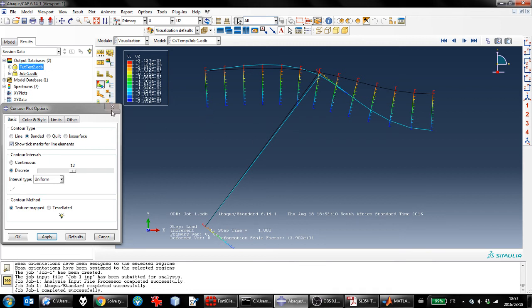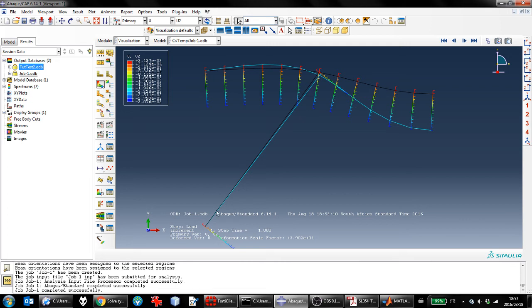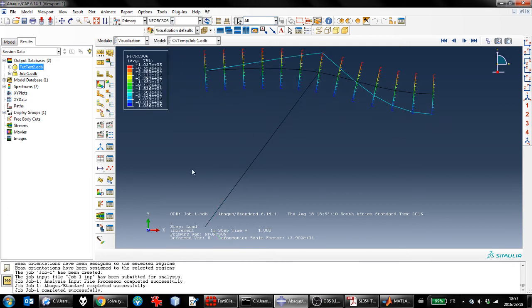More important thing is, because we use the thrust element there, you don't have any bending moments in this member. You can just verify that again by plotting nodal forces. So the correct answer to this problem is exactly treating this thing as having a hinge there. Now I know we talked, Charles, about creating hinges in various ways, but it's important to note, because this type of finite element used for the column doesn't actually have a rotational degree of freedom at the connection, no moment is transferred there. We don't have to create an artificial hinge.